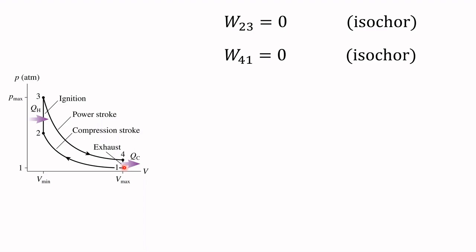But instead of considering what's actually happened, which is the replacement of hot gas and reactant products with fresh, cooler air and reactant products, we imagine that we stuck with the same particles and allowed them to shed heat isochorically. Because if you look at the beginning of the exhaust stroke and the end of the intake stroke, the volume is the same at those 2 points anyway. So you can just model it as an isochoric process.